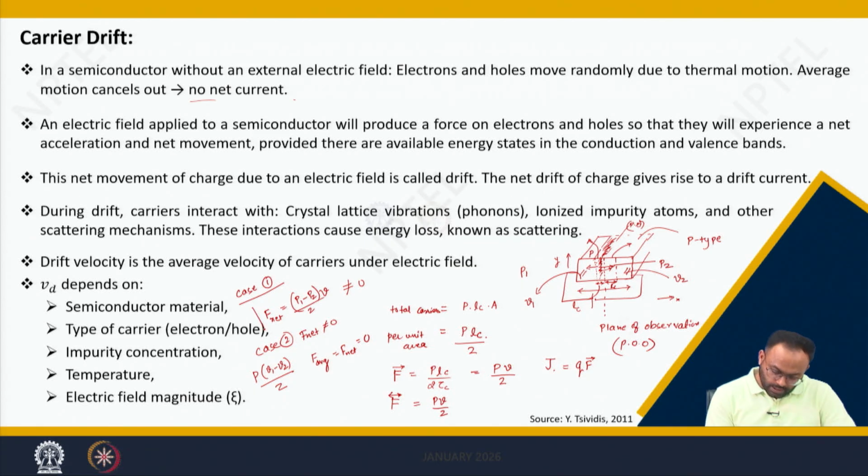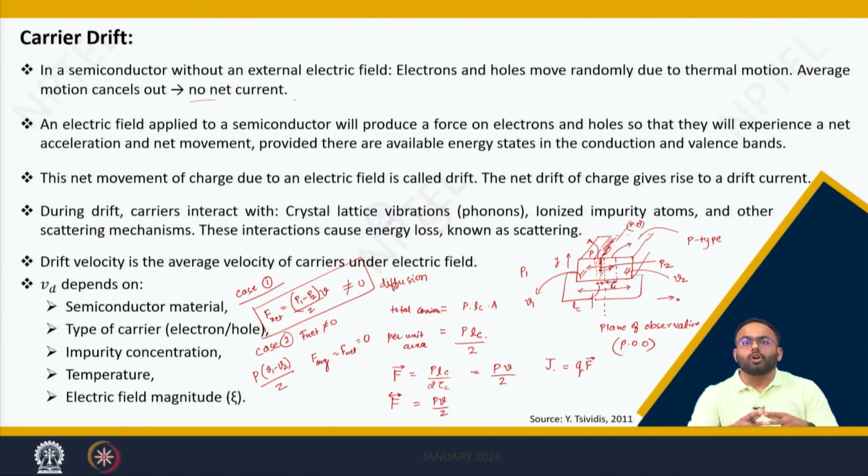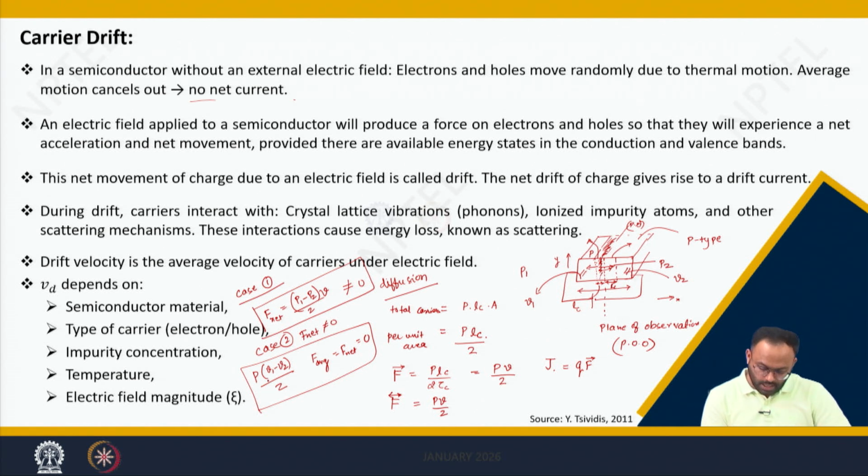The first case is basically diffusion, where even without applying an external voltage there is a net flux because of the concentration gradient. That is what is called diffusion. Similarly, this second case is called drift. In a uniform sample, if you apply a voltage, then there is a velocity difference and hence you will get a net flux. The net flux will give you a net current.